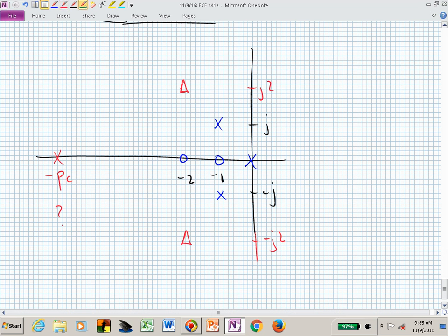We know how to calculate all of the angles of the poles and zeros to that triangle. This is just trigonometry. We can compute this angle, and let's call that angle theta p sub 1. That pole factor contributes that angle.